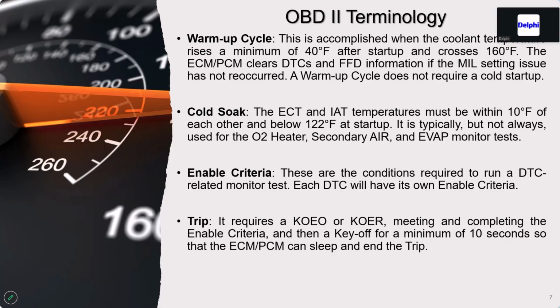But remember, a trip does not end until you turn the key off. And I always say a minimum of 10 seconds, but the simple way to remember is if your scan tool says no data available, that trip has ended. If you don't do this and you start the key up right away, you turn it off, and within a few seconds you turn it back on, the PCM hasn't gone to sleep, you're going to be wasting your time because you are in the previous trip and you may have hit the maximum time already and you may have exceeded the criteria at that time. You can't make it work. So keep these 4 things in mind.